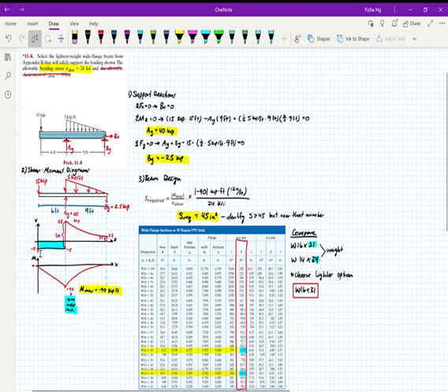We are at negative 15, we're just going to continue to be at negative 15 until something happens, which is that AY is another external point load, which is pointing up, so it's going to cause a positive jump. So from negative 15, we have a positive jump of 40 up to 25. And then from there, we have this triangular load, which, if you remember, you're increasing your order each time. So the triangle is order 1. It's like a line. You're going to increase the order to an order 2, which is a quadratic. Our distributed load is pointing down, which means it's going to be a decreasing quadratic.